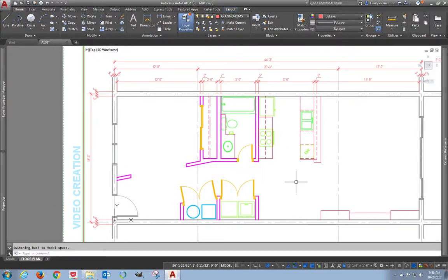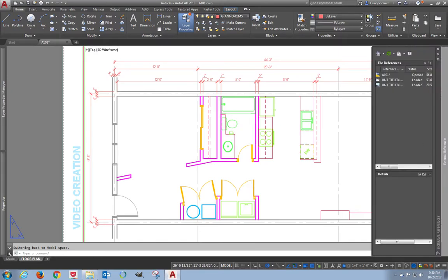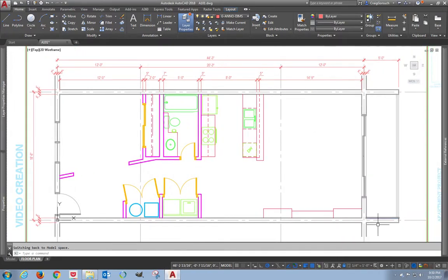And here's where I'm instantly going to break one of my first rules. Well, I'm not exactly breaking it, but I'm going to stretch it a little bit. I told you that we don't normally want dimensions running right through the middle of a plan. Well, I don't want to take the dimensions for these rooms and pull them all the way out to the edge of the drawing. So I'll have these rooms going right through here.